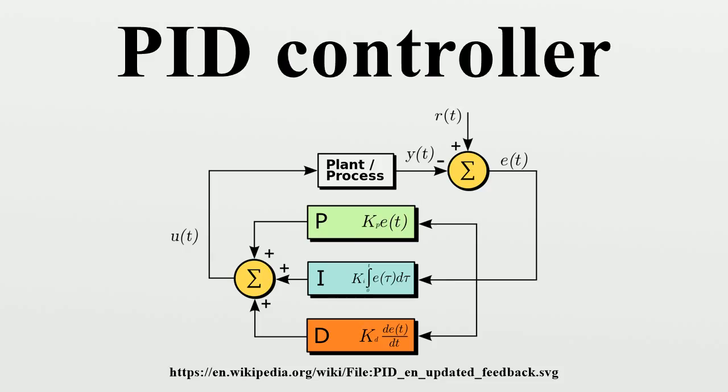Electronic analog PID control loops were often found within more complex electronic systems, for example, the head positioning of a disk drive, the power conditioning of a power supply, or even the movement detection circuit of a modern seismometer. Nowadays, electronic controllers have largely been replaced by digital controllers implemented with microcontrollers or FPGAs. However, analog PID controllers are still used in niche applications requiring high bandwidth and low noise performance, such as laser diode controllers.